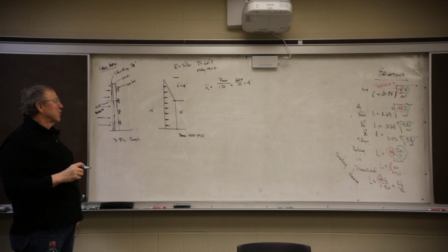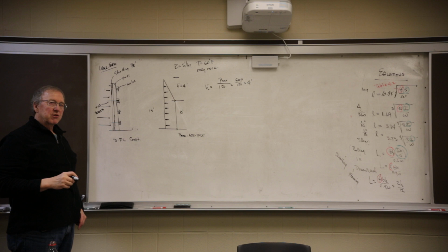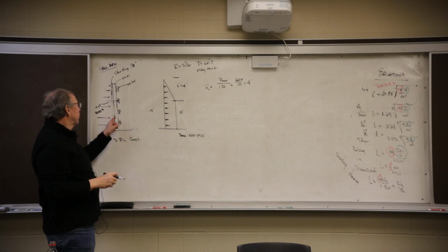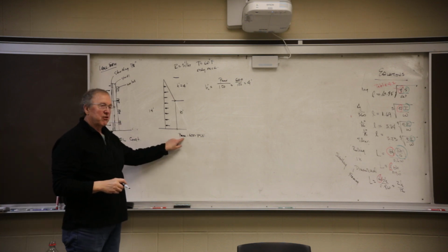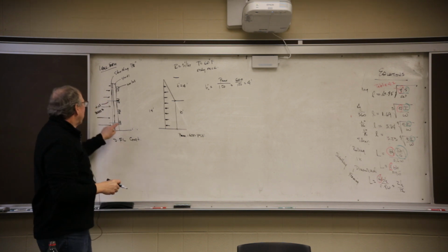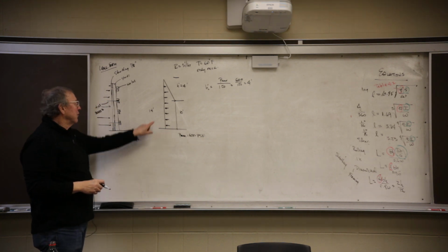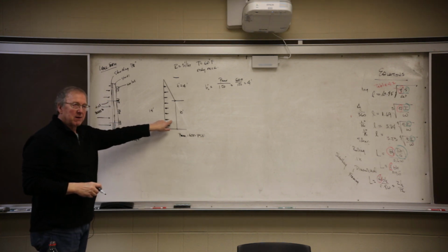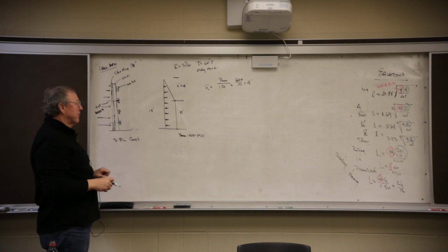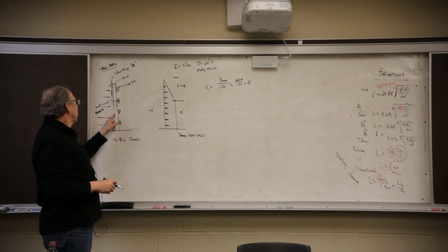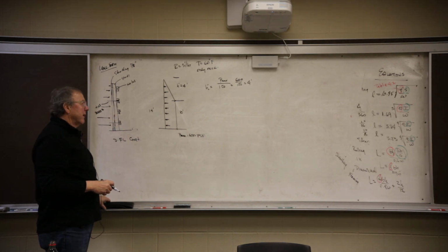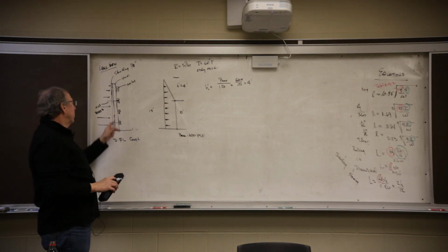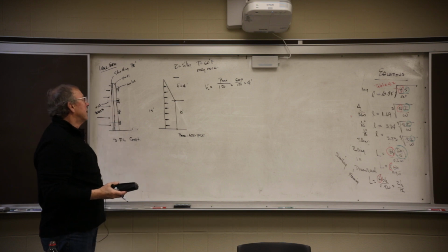So we're going to use 2 different ways of figuring loads. For sheathing and studs, we're going to use P max. For wales and wall ties, we're going to use the loading diagram. So we'll be using this for that. We're going to go ahead and worry about designing the sheathing and the studs, and then we're going to move into the wales and the wall ties.